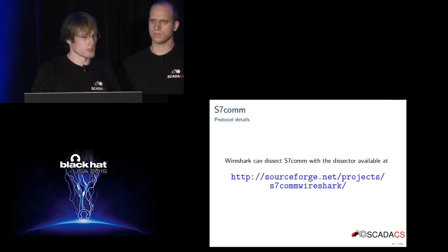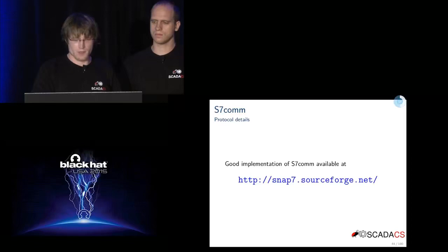If you are interested in S7comm, the open source community has done a great job reverse engineering this protocol. There is a Wireshark dissector, which is pretty good. Also, there is an implementation of the S7comm protocol available called Snap7.